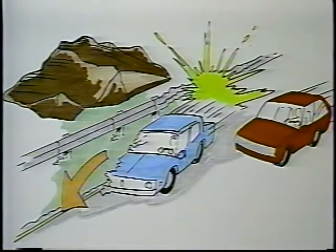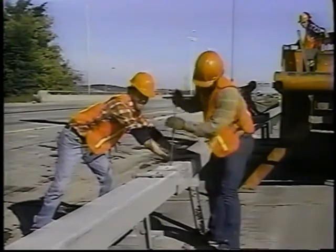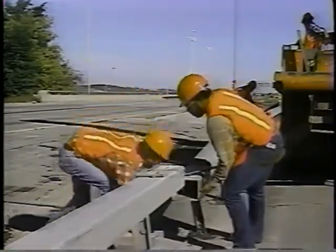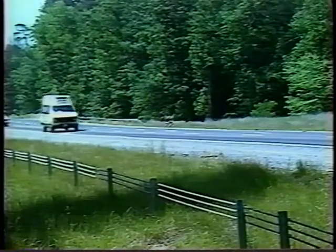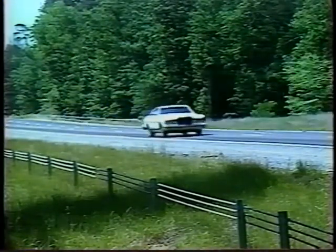A barrier must not be installed so close to a traffic lane that an impacting vehicle could be redirected back into the traffic flow, or the barrier itself be deflected into the normal traffic lane. Finally, the required maintenance and the cost of the system need to be considered when selecting a traffic barrier. In general, flexible systems that are more forgiving when they're hit are best for the driver.